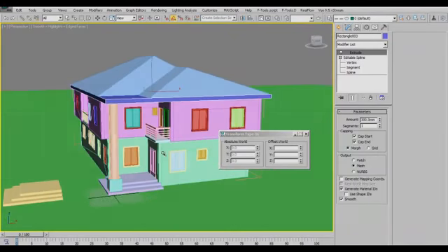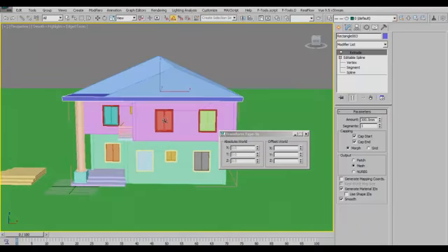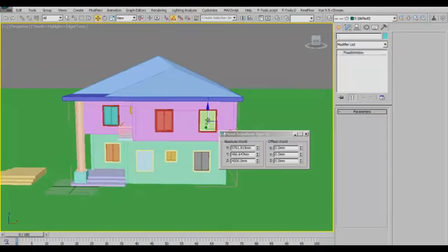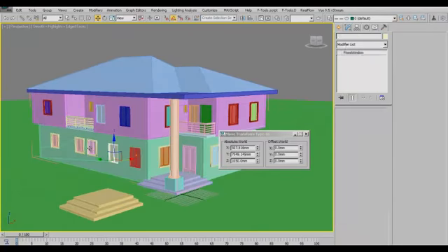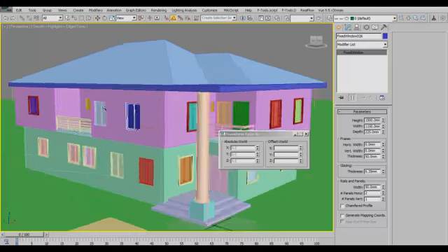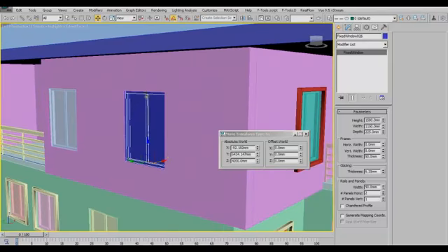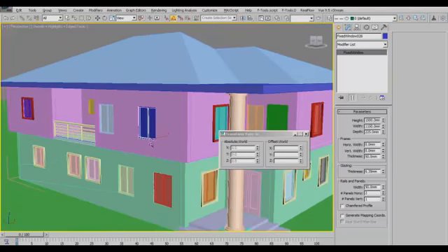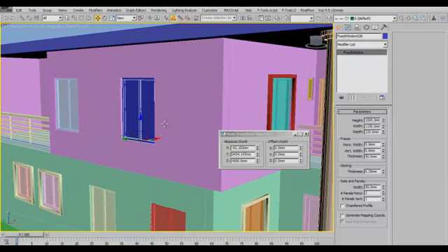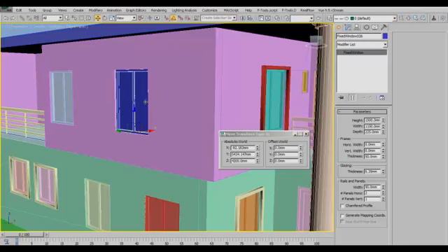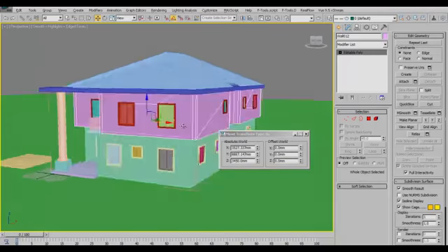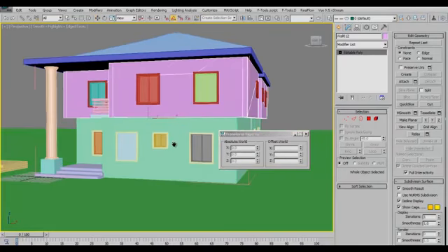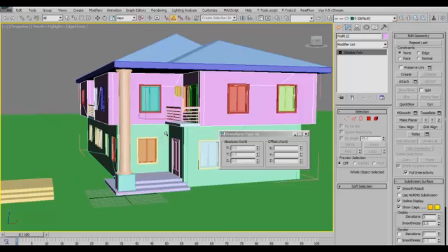Then we start texturing, adding maps, adding textures, and I'll show you how to get textures for the AEC objects, because the AEC objects already have their own sub-object, you know, because this is going to be aluminum and this is going to be glass, and it's a single object, and there are materials already pre-made for it by Autodesk, and you can just apply that and adjust it however you want. Then for the walls, we'll just apply some materials and go ahead with the rendering after that.